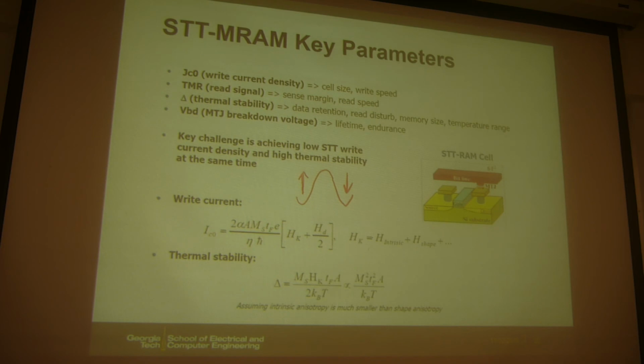As we discussed before, if you recall this principle for the SRAM, and you recall the 6-transistor SRAM cell, the read and write conflict with each other, right? Fundamentally, this is a problem for all kinds of memory, because for the write operation you want to change the data, and for the read operation you don't want to change the data. You want to maintain this for a long time. So then this is a conflict.